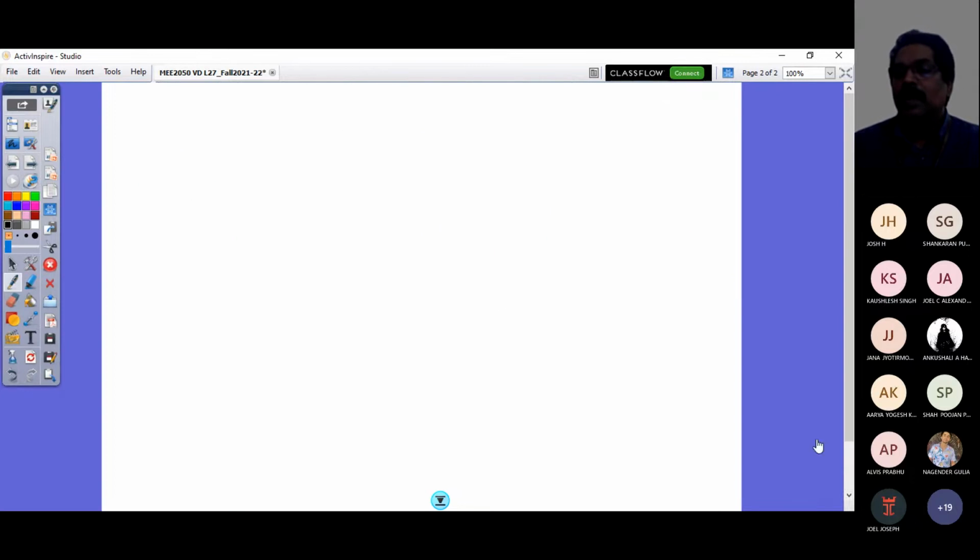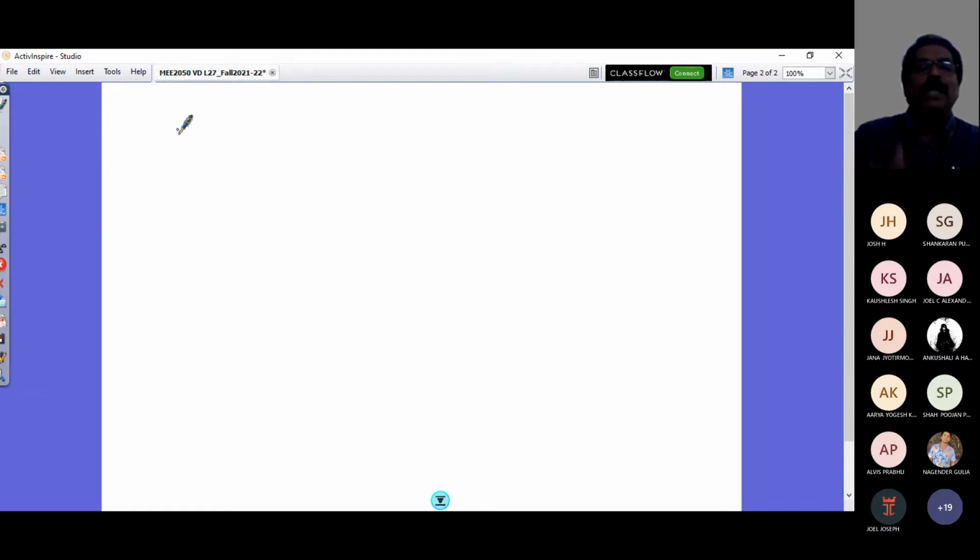So that's a half car model. Half car model means you can have a half car either by slicing your vehicle by the symmetry plane XZ, or you can slice the vehicle by the YZ plane through the CG. I'm going to take the second case, and my vehicle is defined like this. So I will have my half car where this represents the axle, where the front axle and rear axle wheels are collapsed and taken together.